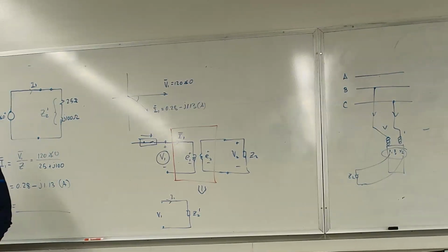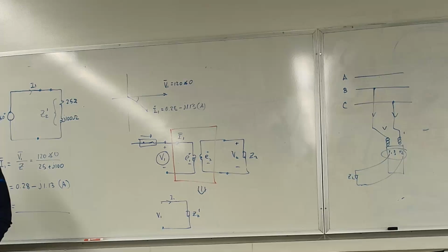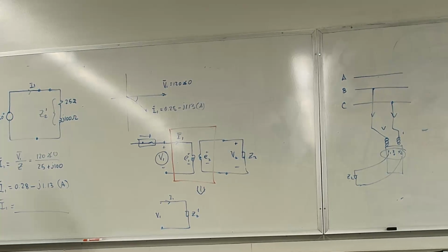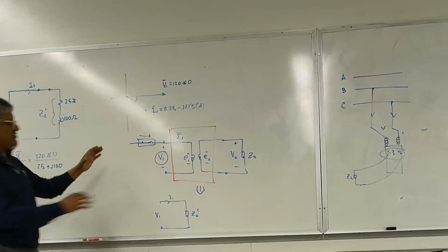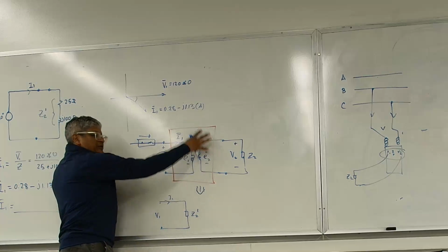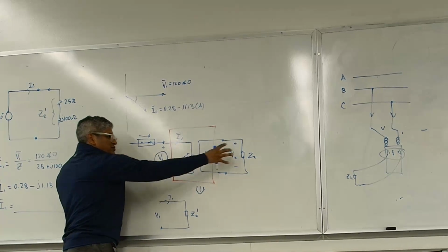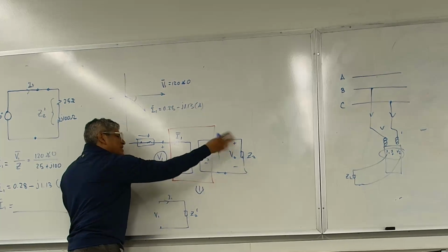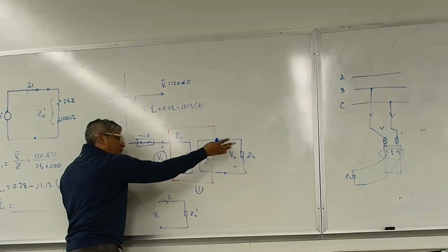Okay, so it's just load Z2 after being converted to the primary side. Correct. The next example, I will show you that. The power, because this is an ideal transformer, I'm not losing any power, the power stays the same. Because the transformer right here, this box, is not accounting for any losses, right? So like you said, all I did is, oh man, I can do the analysis on the secondary side, but what would I do then?